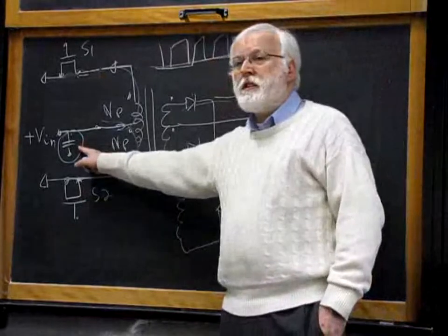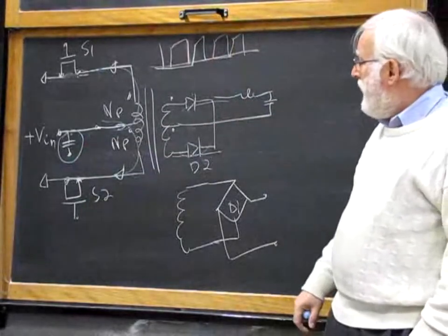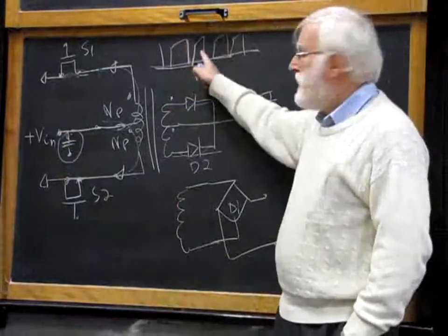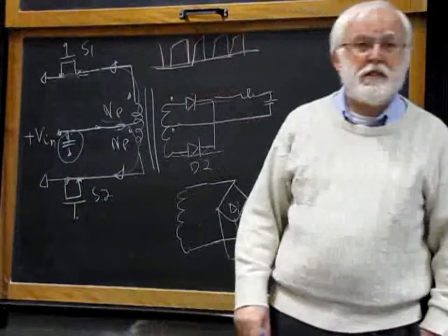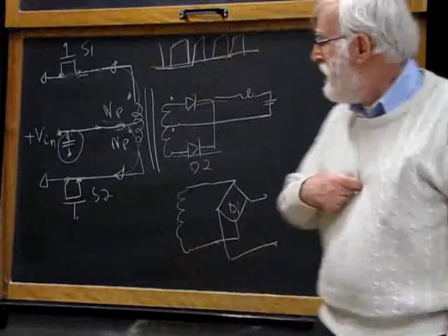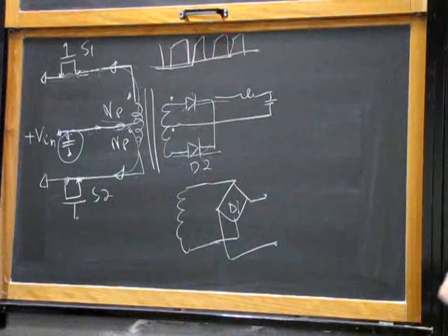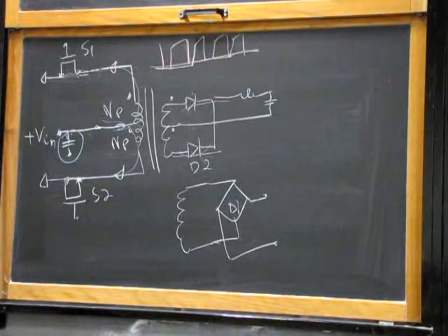This capacitor works at the same frequency as the buck converter is working. And the current that flows through this capacitor is the current given by all these pulses. So the duty cycle that this capacitor sees is the buck duty cycle. It's not the switch duty cycle. It's not the transformer duty cycle. Okay? Those are basically the very same considerations I made for both full bridge and half bridge.